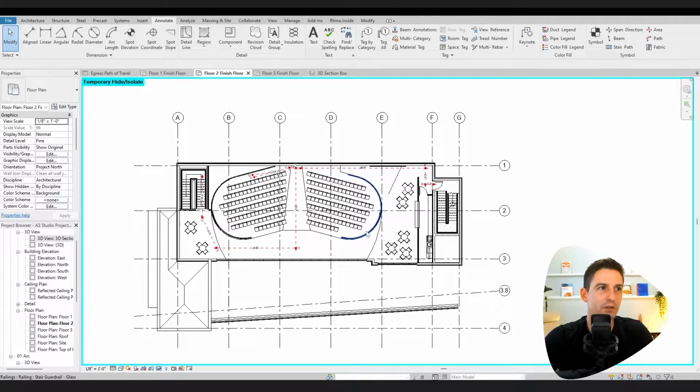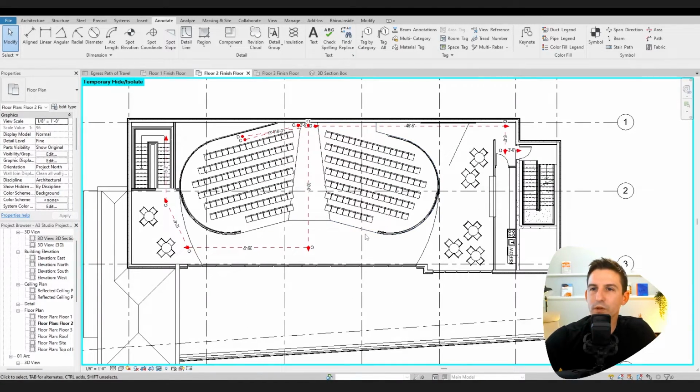The idea that I try and do is just put them on opposite ends. Just think like any hotel that you've been in, right, is probably a double stacked corridor. So you got rooms on either side of the hall, and capping off the ends of that hall is typically an emergency exit stairwell on either side, which basically guarantees that you have a really short common path of travel and you don't have any dead ends with that kind of design. So I highly recommend doing something like that to keep things simple if you are new to this.